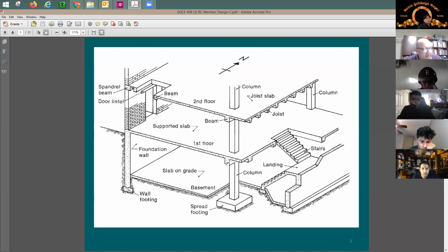And if you think here about this beam from the way it is drawn, this beam is continuous. It's coming from a column to a column. Very similar to this beam. From this column, it is running all the way across to this column. And then here we have some beams. If you look here at these beams, you should say, maybe I'm expecting a beam to be running across like this. These beams are supported by columns. And then at the end, this column is supported by a footing.